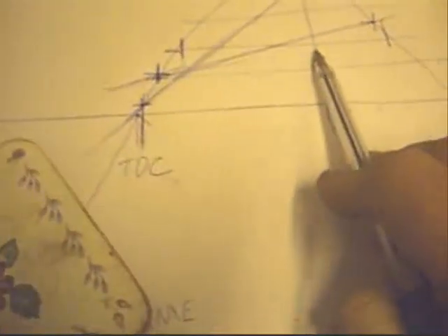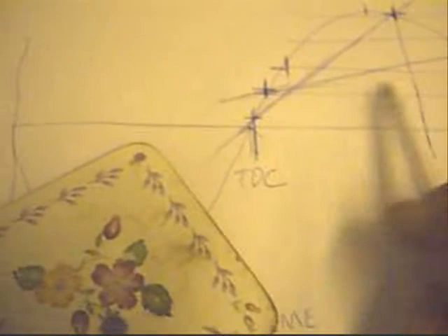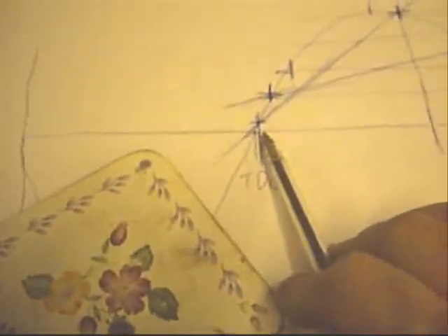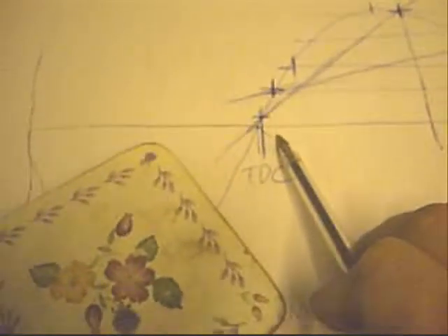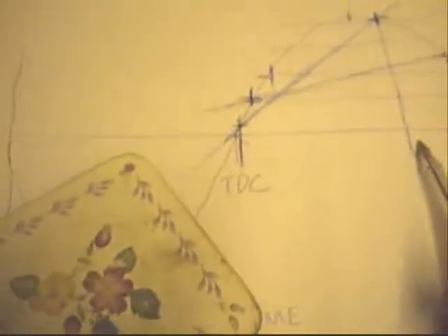Even if the time between the turn on and turn off points is the same, the closer the turn on point is to top dead centre, the more power you get transferred to the magnet, to the rotor, for the same amount of current being drawn from the battery. Ergo, it's more efficient. That's in theory anyway.